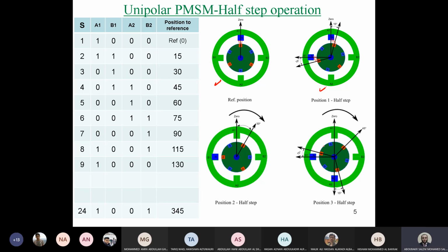In this case, you will have high power. So the benefit of using bipolar is the higher power. You can make higher torque and higher power. This is why the bipolar is used compared to unipolar to obtain high power. And also, in general, permanent magnet compared to variable reluctance can be used for higher power.